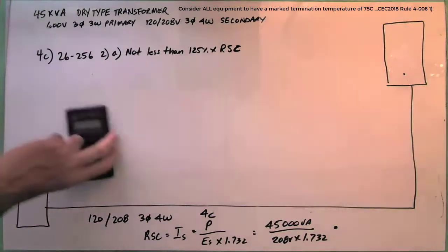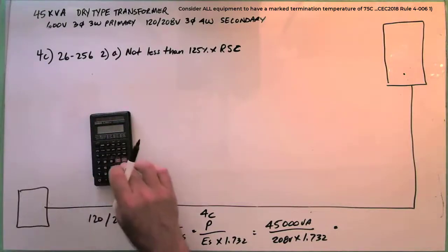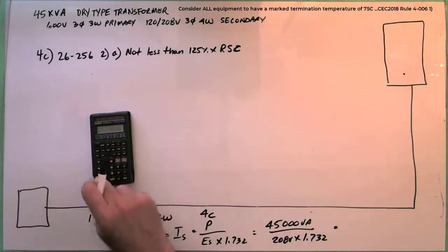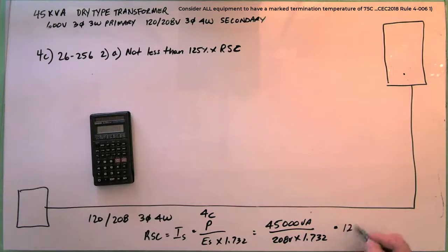I can go to my transformer card, or you just take your calculator, P over E, and then root 3. You get 124.911 amps. Sorry, that's my rated current. So on the transformer card, it'll show 125.